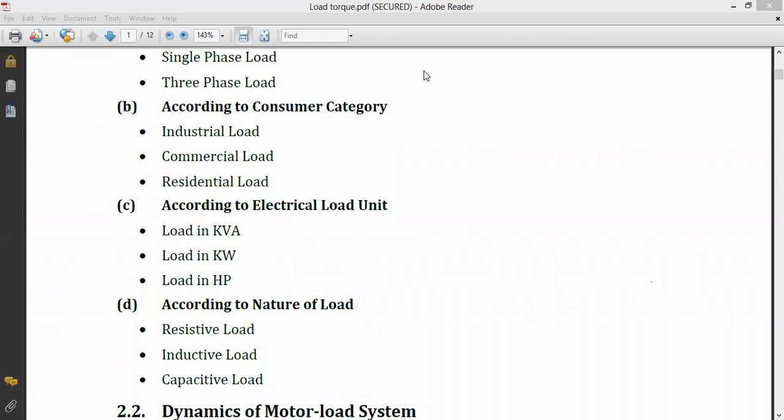You all know from our previous semesters, like in 4th, 5th and 6th semester, you discussed that in case of a resistive circuit, there is no lead or lag in the current. In case of resistance, the power factor, that is the PF, is equal to 1, because power factor means the cosine of the angle between the voltage and the current. And the angle between the voltage and the current in a resistive circuit is equal to 0, and hence the power factor is equal to 1.